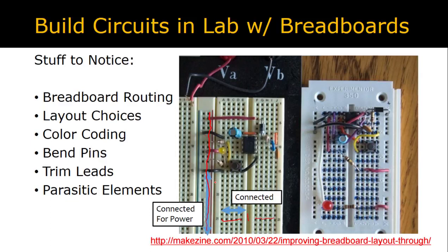Having established that underlying feature of breadboards, we might ask, why is the circuit on the left so much better than the one on the right, in my estimation? The answer is that it's easier to tell what things are connected to each other in the circuit on the left, and also it's easier to disassemble and reassemble the circuit on the left in case anything goes wrong. In the circuit on the right, if I were to look at the orange wire, I have to carefully scrutinize a number of intersections and crossovers and cross-unders to tell what two things it connects to. And if I wanted to remove that orange wire, I would need to take out 3 other wires to get it in and out. That's not true of any wire in the circuit on the left.